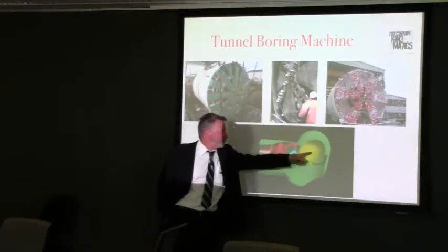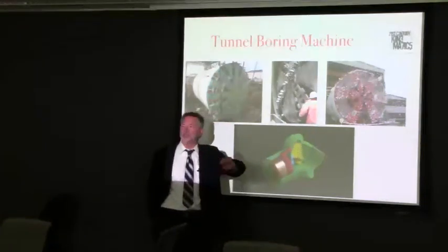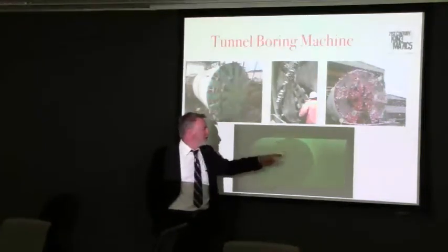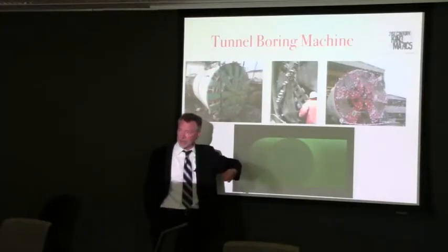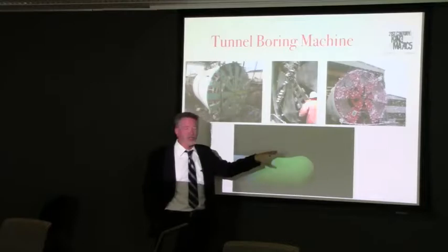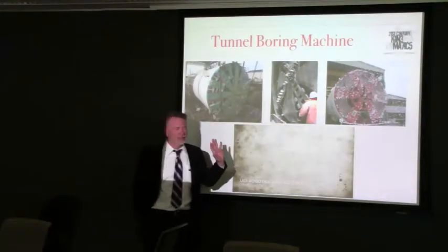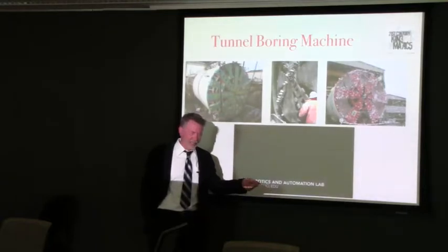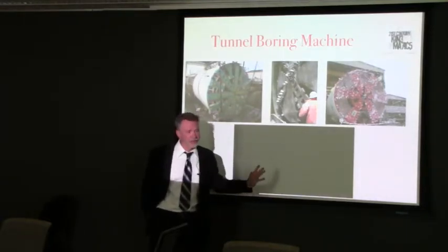And it's doing it in response to line pressure on this plate. So essentially what you do is you open the pressure, it pushes on that plate and it opens the port. When you close the hydraulic line, that reduces the pressure and the port closes. Did I say that in reverse? You turn the line pressure on, it opens the port. Turn the line pressure off, it closes the port.